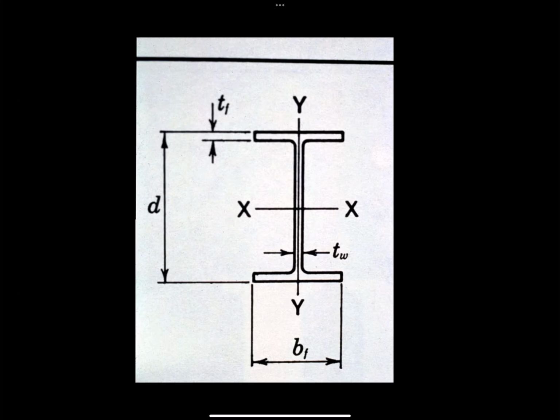So if we are using standard W sections, then the typical maximum rule of span, absolutely standard steel structure, is around 36 feet. So you could have 36-foot square structural bays, and you would be pretty standard steel structure. The rule of thumb for the depth of beams is 1/20th of the span. So if I have a span of 20 feet, my beam is 1 foot deep.